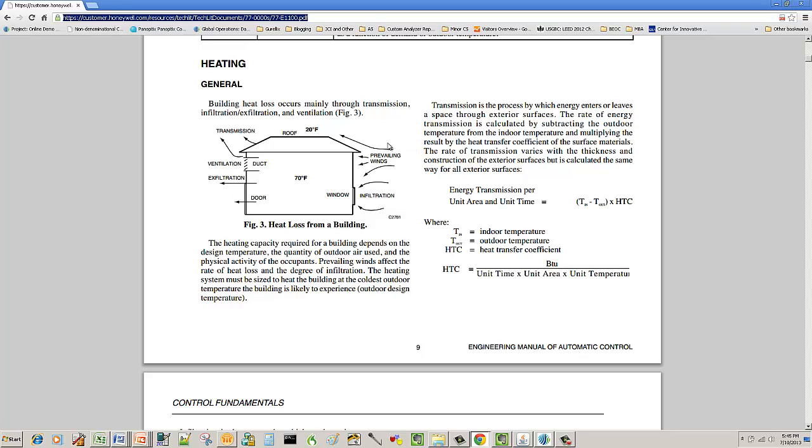If it's 100 degrees or if it's 20 degrees outside, we want to keep what's called our envelope. That's this exterior of the building. We want to keep our envelope positive. We want to keep our pressure positive, so effectively we're creating a bubble and we're keeping pollutants, allergens, things of that nature from entering the building, but we're also keeping thermal gain or thermal loss from the building. Now we see here we've got some ventilation that may be leaving.